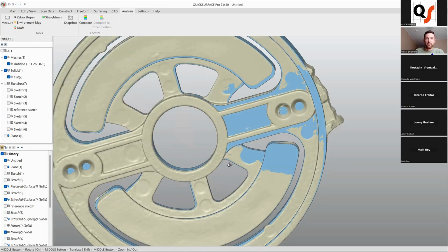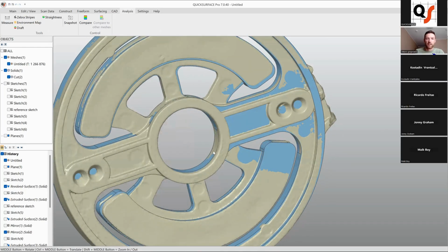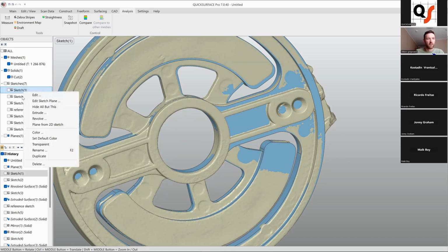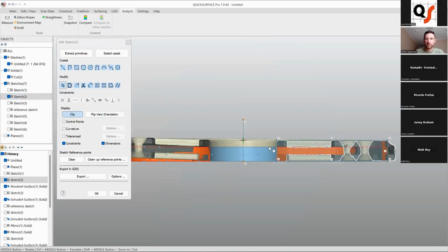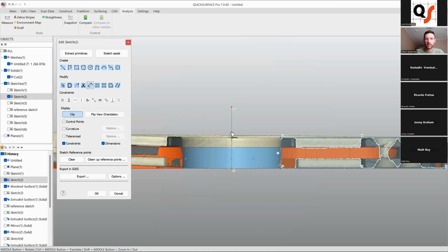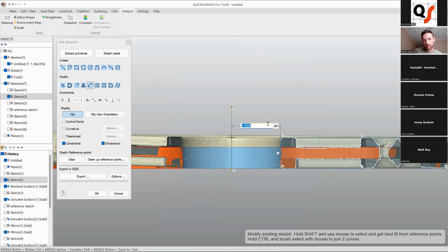if you are recreating some parts that should fit on axles or something, you should consider the diameters of seats. So, for example, here we have a pitch diameter. At the moment we have almost 16 millimeters, a bit under, so probably it should be 16 or a bit oversized.